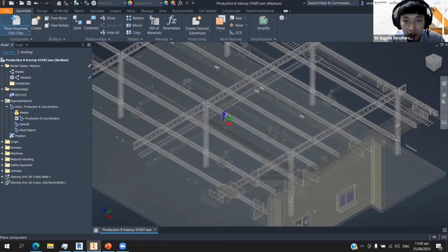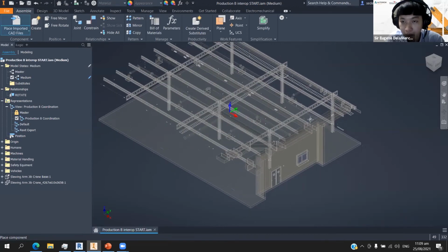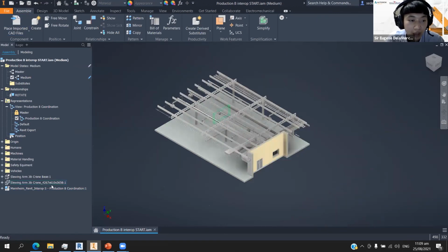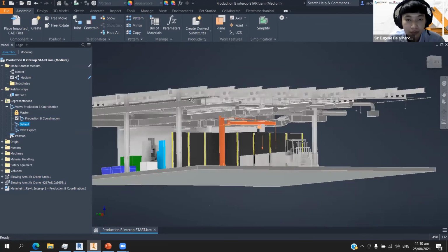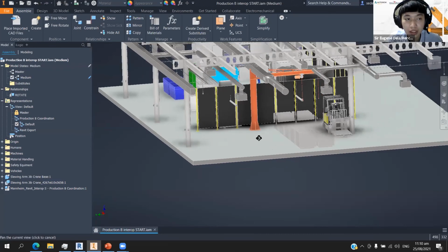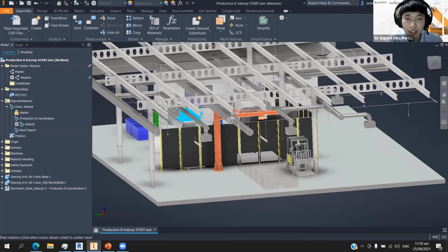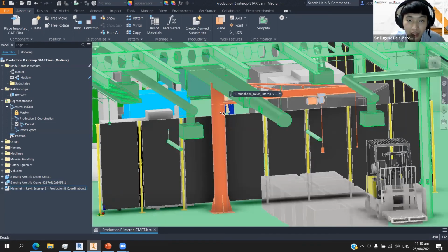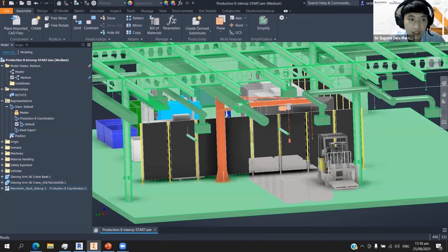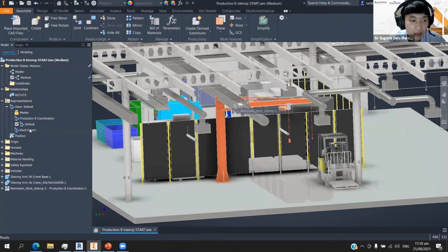As you can see here, we can place this grounded at the origin, and then press escape to get only one instance of this Revit file. So here we already have the Inventor models ready to be placed by just selecting the visibility of it. But we have the default view, as you can see here. The default view now has the Inventor models activated. As we explore this model, we can now see a clash here, the clash that includes the HVAC system as well as our crane. For this instance, we decided that the crane will stay in place, and we are going to be moving the HVAC system. So I have here the Revit export.